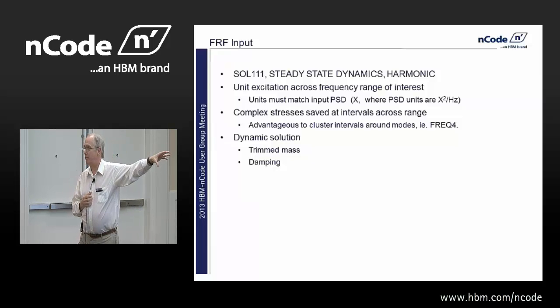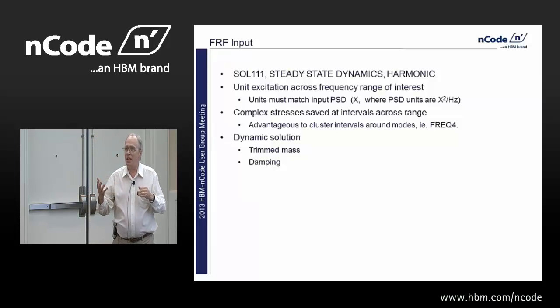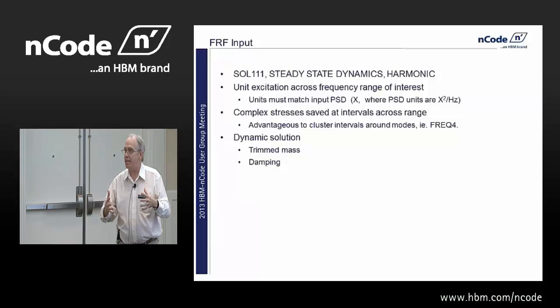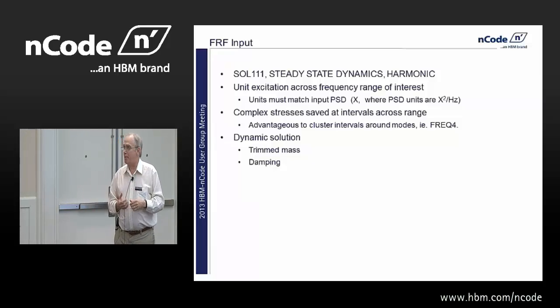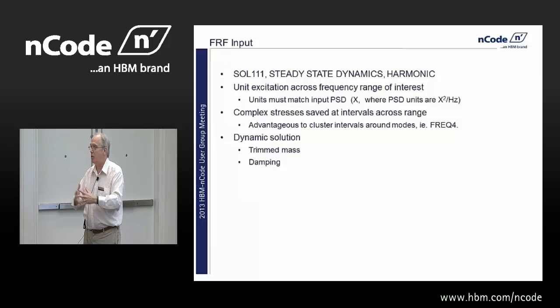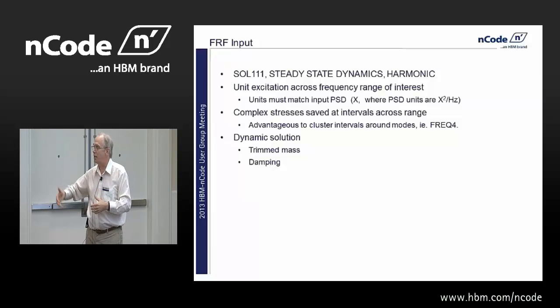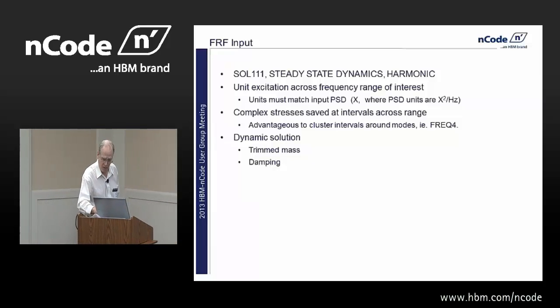Secondly, we need damping. And that actually came up earlier in conversations, that the one thing that makes fatigue look like an exact science is damping. And so we need to worry about damping in the system. We're going to put the damping in the FE analysis, but that eventually comes downstream to DesignLife in terms of what the excitations look like. So this is our FE input.